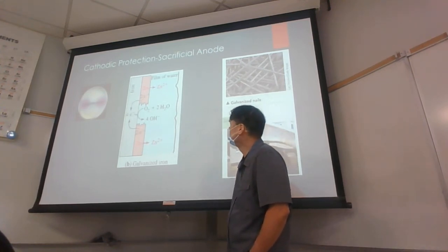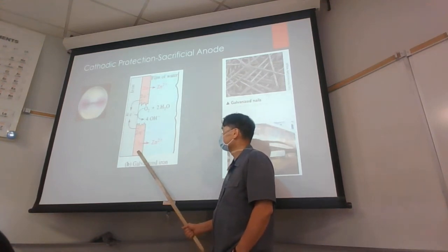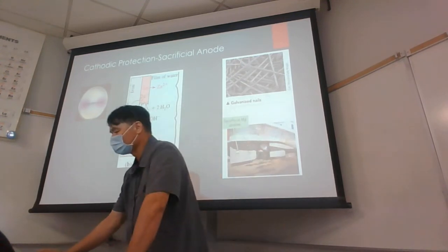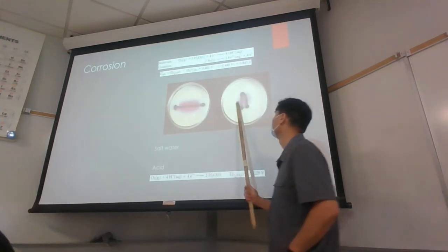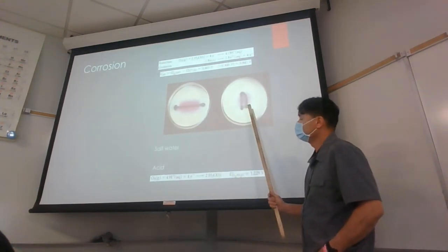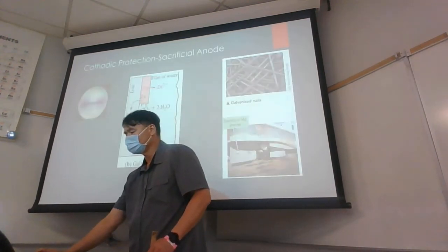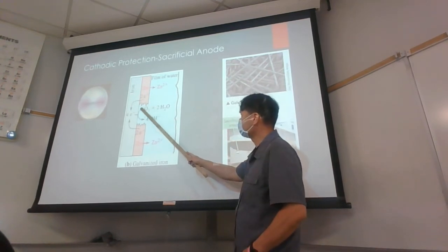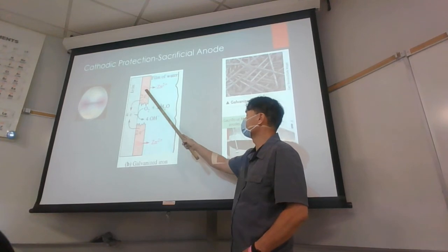Now, this is called a sacrificial anode because we're taking the normal anode, which would have been iron, here. You can see the corrosion of the iron here, here. And then using an alternate anode, which in this case is zinc. That's going to protect the underlying iron. So oxygen might try to attack the iron directly, but it's not going to be successful because it's just going to take from the zinc.